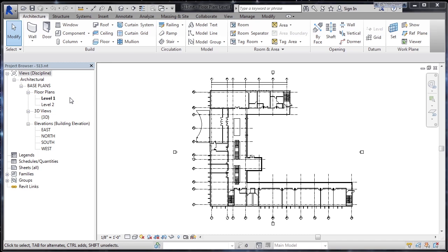In this lesson, we'll discuss using linked CAD files, specifically linking in architectural elevations. Now, in previous lessons, we looked at linking in floor plans, and we discussed using Revit as a master file to manage these AutoCAD 2D files. The reason we would do that is we can organize these 2D files in a 3D format so we can actually see a model. So for example, what you're looking at now is a flat 2D floor plan, basically a CAD file that's been referenced in.